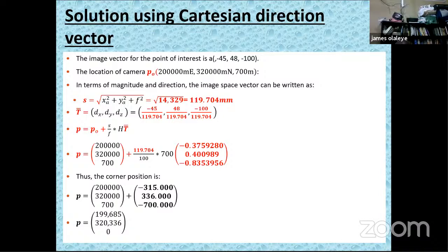Yes. So whatever the resolution is, it is a property of the camera and is fixed at the time of production of the camera. If it's in the ground unit, what name do they call it? We call it GSD, or ground sampling distance. So if you want it to be 3 cm or 5 cm, then it is designed that way, and the distance at which you get that resolution depends on you.